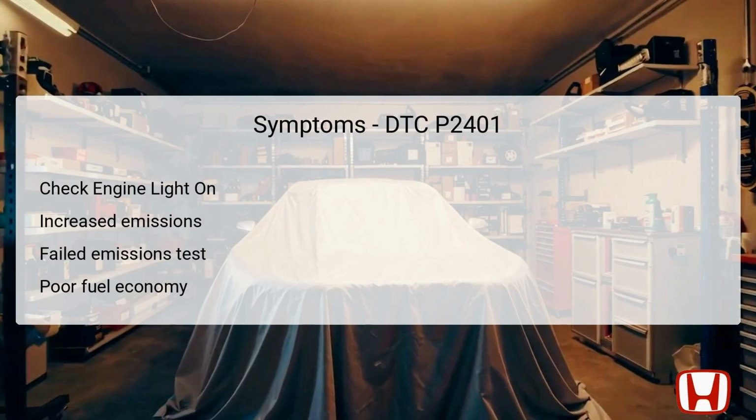This malfunction not only poses environmental concerns, but may also lead to the vehicle failing an emissions test. Drivers might also notice poorer fuel economy, as the combustion process may be inefficient if the EVAP system is not functioning correctly. Overall, the combination of these symptoms underscores the importance of timely diagnosis and repair to restore the vehicle's environmental compliance and operational efficiency.